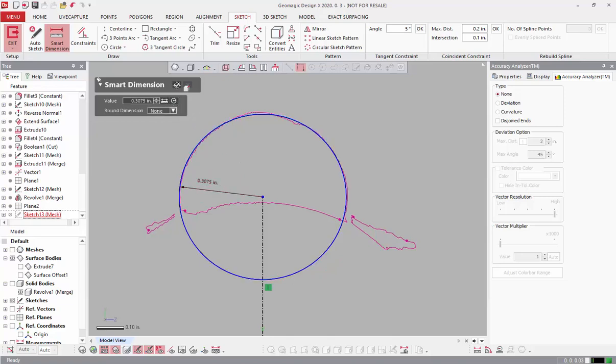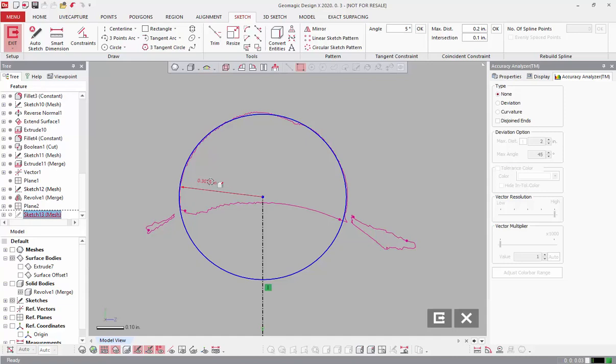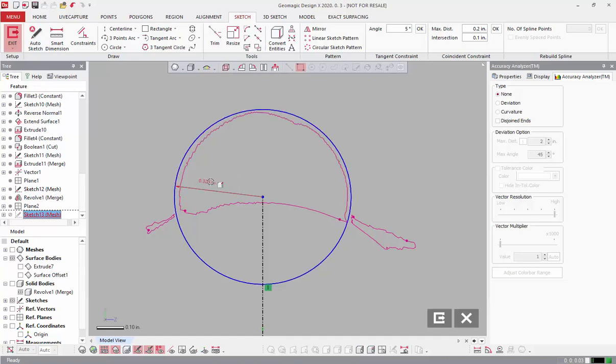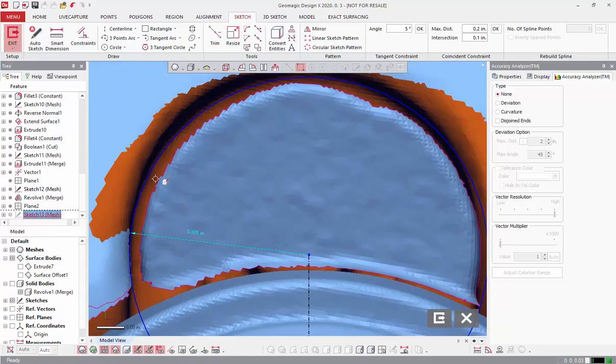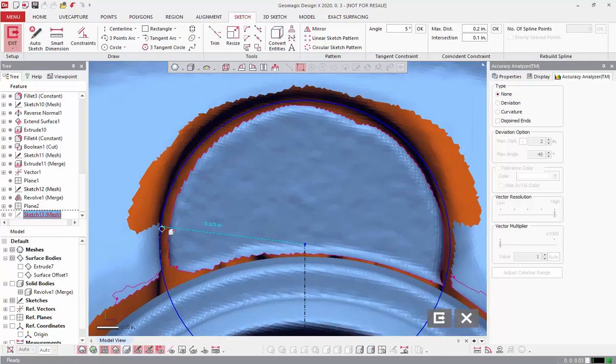if I put a dimension on it, then I can see, well, maybe the original designer's intent was to create a, I don't know, 0.325 fractional. That's probably way too big, but I can choose what value I want to put in there, even though I'm not using perfect data. But if that's close, I know that the real feature there is going to be just a little bit bigger than this currently is, because that feature cuts off on the fillet.